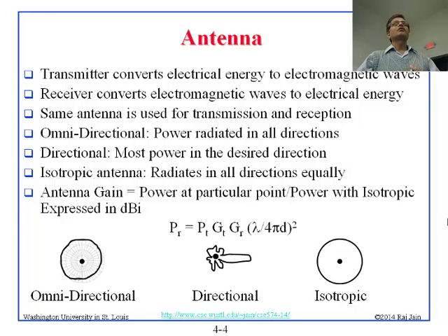Alright? So, for example, if you are given a choice of using 2.4 and 5.8 gigahertz, which one will go farther? Both are allowed in Wi-Fi. Which one will go farther? 2.4. All right. And so that is just natural. People like to use smaller frequencies. 700 megahertz would be even better than 2.4, and 300 would be better than 700, and so on and so forth. And obviously those lower frequencies are not available, or are not available enough.